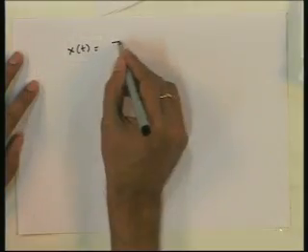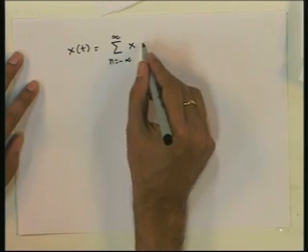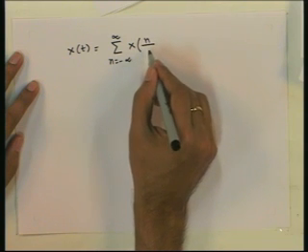As we said, a band limited stochastic process is defined to be a stochastic process for which the power spectral density, the power density spectrum, is band limited. That is, it is 0 outside minus W to W. If that is satisfied, just like a band limited signal, the stochastic process x(t) can be expressed in terms of the samples at n by 2W. 2W is the Nyquist rate.